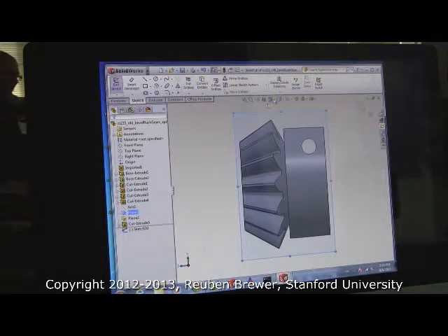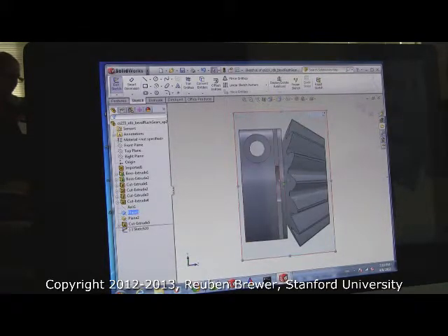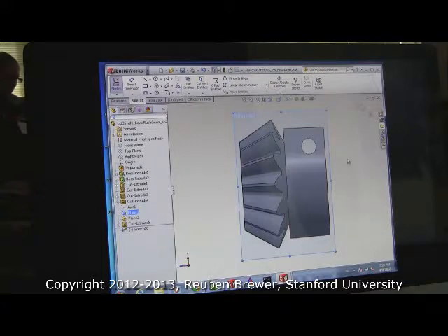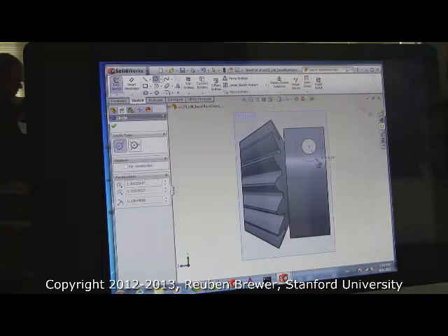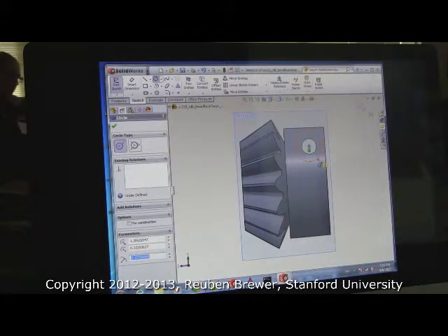Okay. Now say that your gear looked like this. Do you want to sketch on this side? No. So press the normal button if that is the case. Okay. Take a circle, auto-align it with the center, and make it about this big. But we want it to be construction. So turn it into a construction circle for me. Everybody remember how to do that? A little check mark in the bottom left.